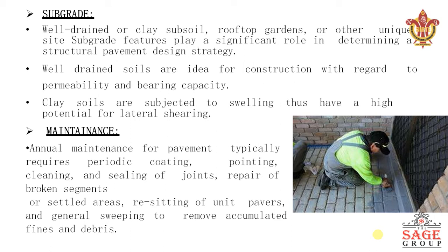The maintenance. Annual maintenance for pavement typically requires periodic coating, pointing, cleaning and sealing of joints, and repair of broken segments. Resetting of unit pavers and general sweeping to remove accumulated fines and debris.